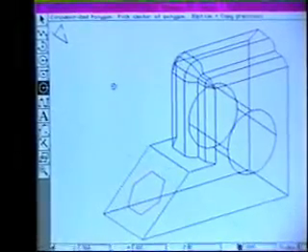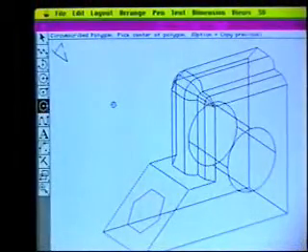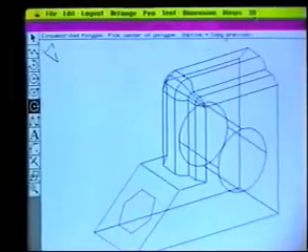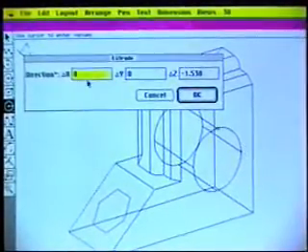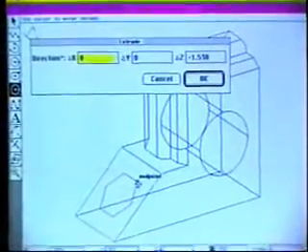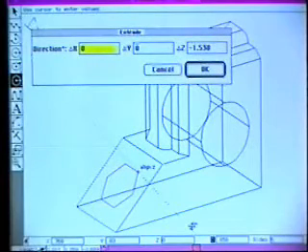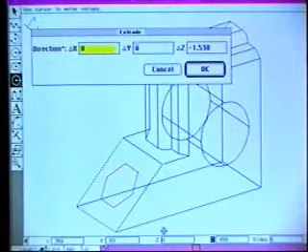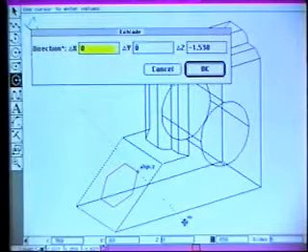Now I want to extrude that hexagon perpendicular to that face. So while it is selected there, I can go up and I can say extrude, and I get this box. And all I need to do really is just grab one of the points and pull, but I need to be careful about what I see, because as I move around here I see a line Z, but as I move more I might see other things such as tangent or other angles. But what I really do want is to see a line Z, because that means I have now moved perpendicular to the plane.